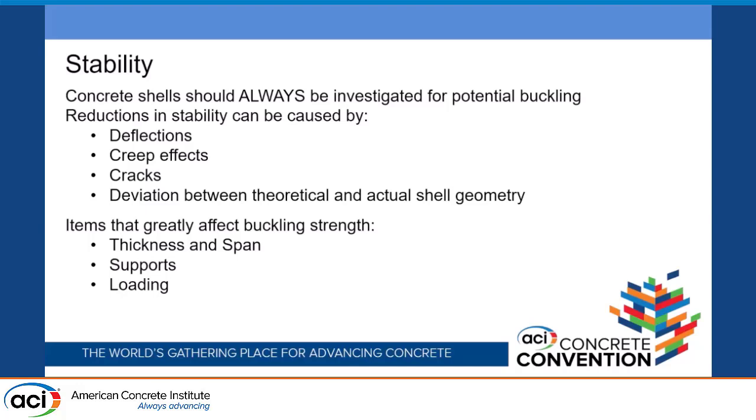Cracking. We design concrete to crack, right? That's how we design it. We design concrete so that it will crack in the right spots. And so we'll see the cracks, and when the cracks get big, then we know we've got a problem, or if they stay small, we don't have a problem. Well, in shell structures, in the tensile zones, as it cracks, we lose some thickness of our member, and we lose some of the modulus of elasticity, so all of a sudden the buckling resistance and the stability go down. So we need to be really careful of that.